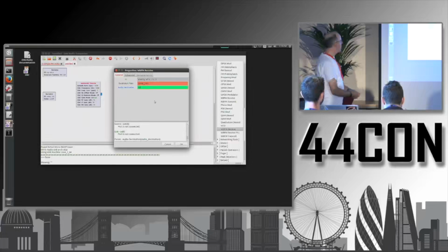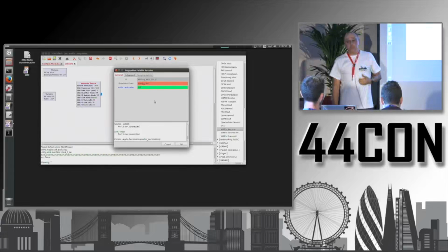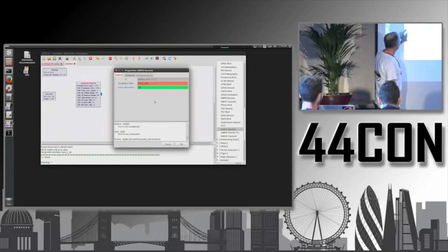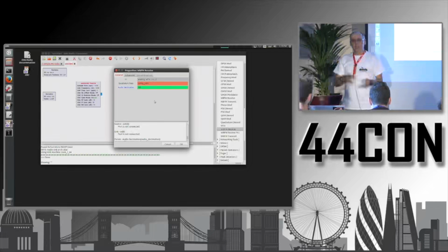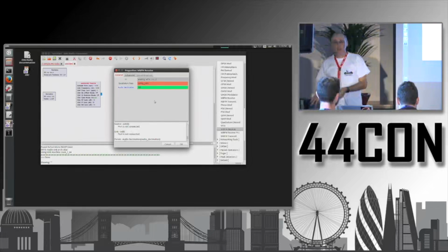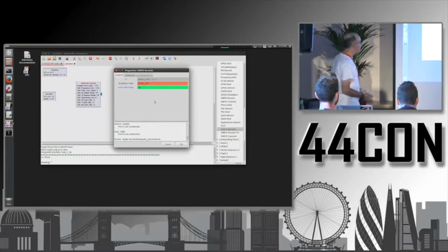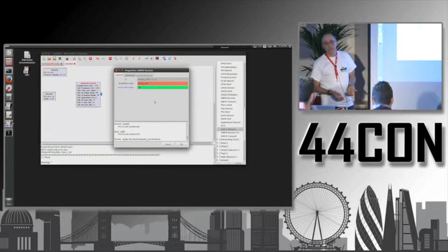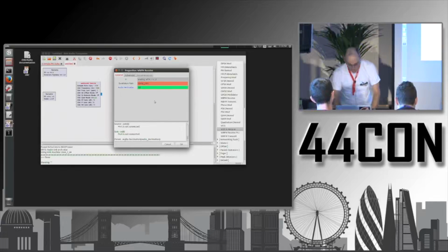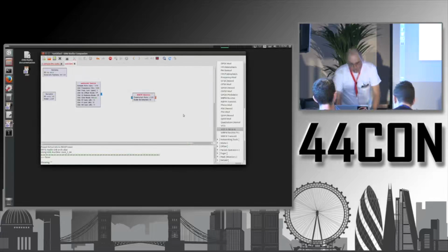And now I can tell you why I selected here as a sample rate 1,920,000, because if I divide that by 40, then I end up with 48,000, okay, 48 kilohertz. And 48 kilohertz is a sampling rate that is often used for audio. Okay, so we can close that block.